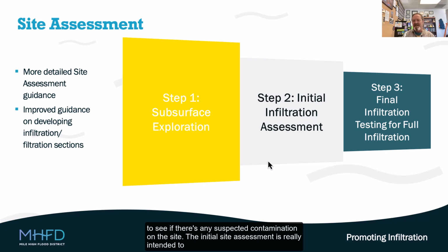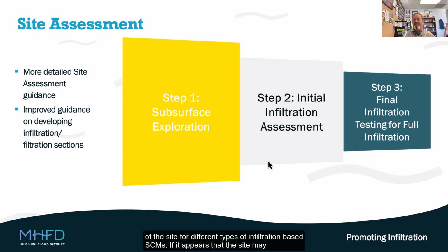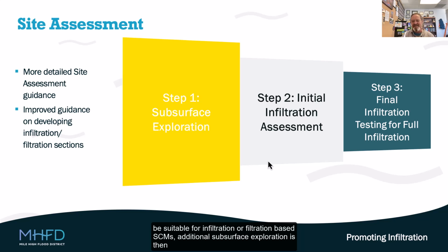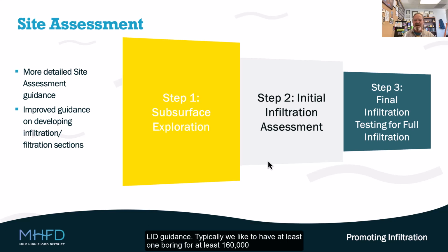The initial site assessment is really intended to identify opportunities for runoff reduction practices and to provide preliminary information on the suitability of the site for different types of infiltration-based SCMs. If it appears that the site may be suitable for infiltration or filtration-based SCMs, additional subsurface exploration is then conducted, and that could include an initial assessment with boreholes or pits, to test out the permeability of the subsurface following guidelines from the state of Michigan's LID guidance.